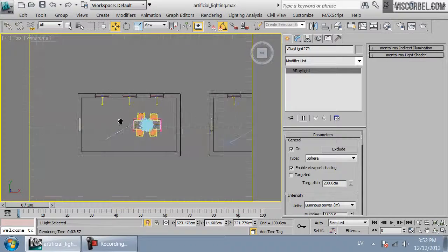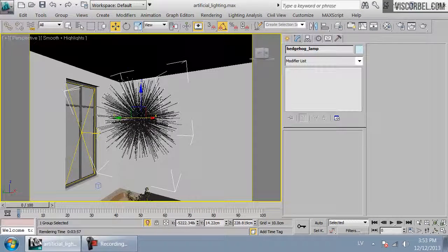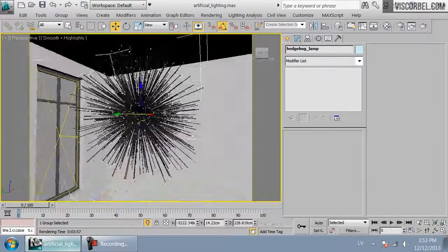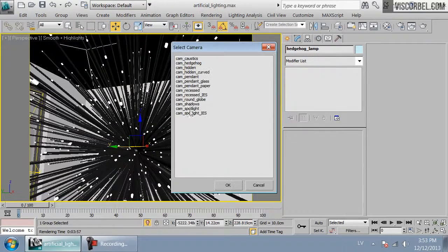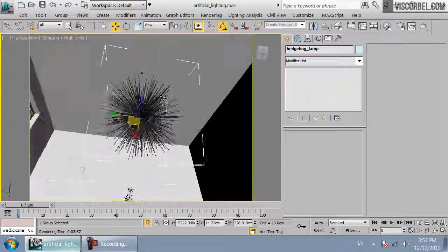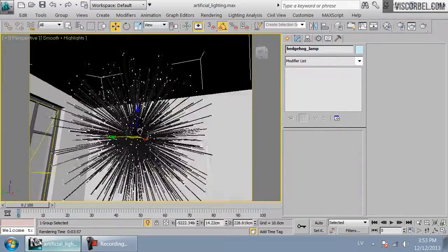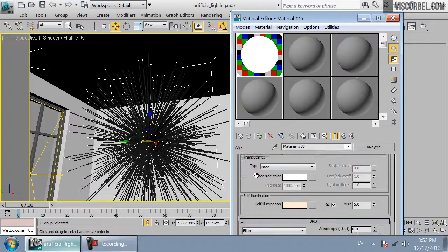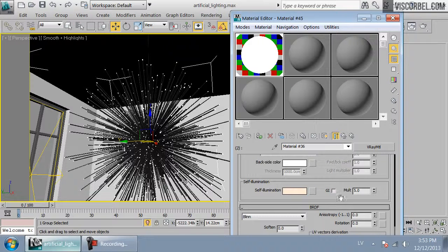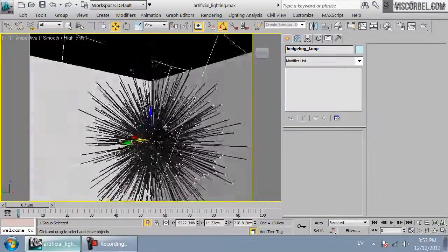Sometimes there are lights that have tons of small LED lamps, like maybe this lamp here. Basically you have this weird hedgehog shape with small LED lamps at the ends of those sticks. And it would not be reasonable to light it by creating these hundreds of light sources and expecting the scene to render quickly. So what I do instead is I create a material with some self-illumination, bump up the multiplier a bit, turn off the GI, and basically you have this bright material that's not really illuminating anything else except the object itself.